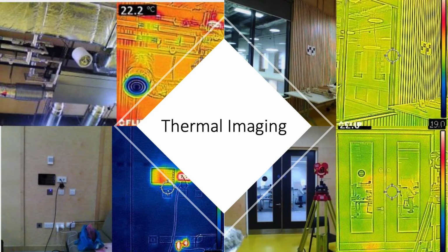And from the bottom left image, we could conclude that the electrical sockets appear to be at a temperature significantly higher than the internal wall where they are installed, by about 36%. A replacement socket with better heat insulation could be considered. Finally, from the top left image, we could tell that apart from the bending bit and the openings, the HVAC system remained at a temperature very similar to the indoor temperature, suggesting a pretty decent insulation.